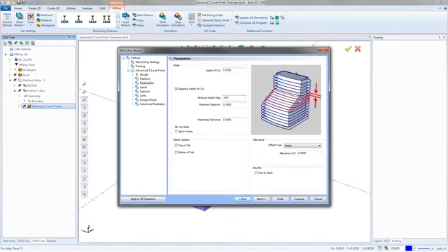When we get down into here, we have to start breaking it up because of this angle. The distance from here depth-wise in the Z is still 20 thousandths between every one of them, but the spread, the full pull that it has to get all the way around that area, we want it to be a bit tighter. So you can go in and give it a better depth step as well as a step over, because the Z-level finish and the advanced Z-level finish normally don't have a step over amount as well.